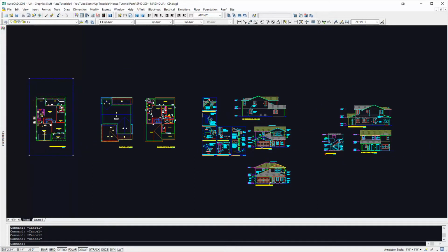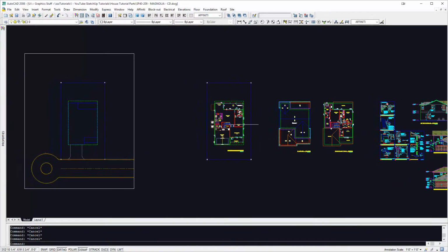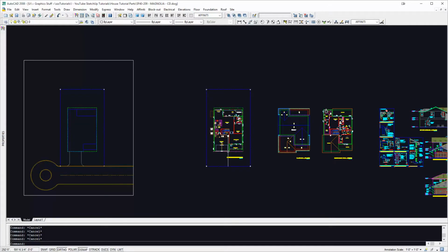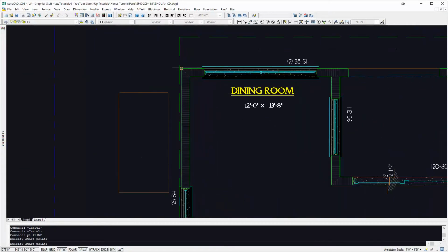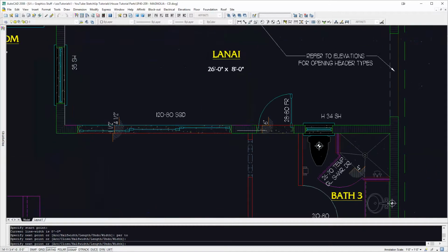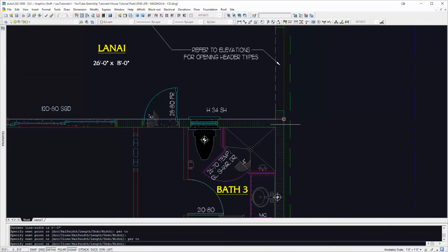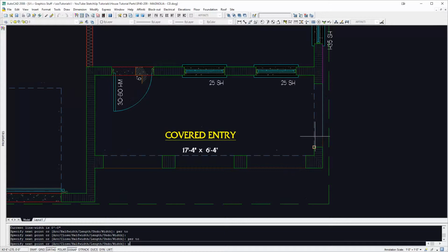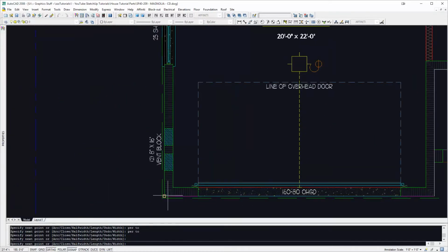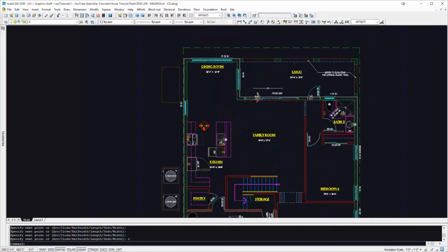So the first thing that I do is I create polylines around the house to be able to extrude and create our basic massing model, and that's really where we start from. So what I want to do is make sure I'm on the 0 layer, go to my polyline command, and follow around the AC space. So we're just going to go through, create a polyline of our AC space, then we're going to come back and do our porches and our columns, and I'm going to show you really two different ways to do columns.